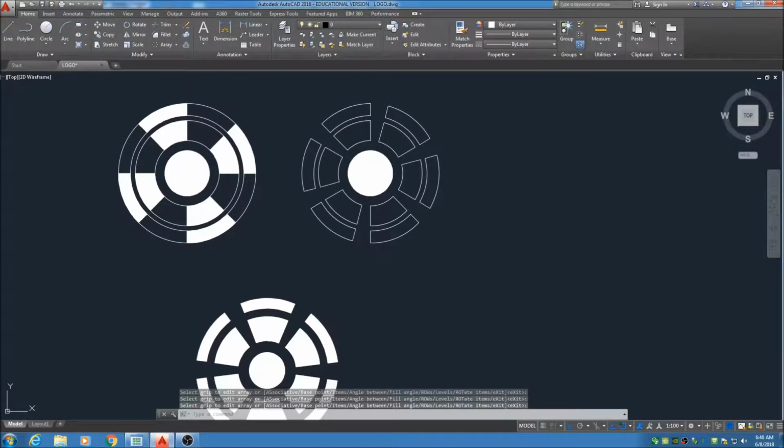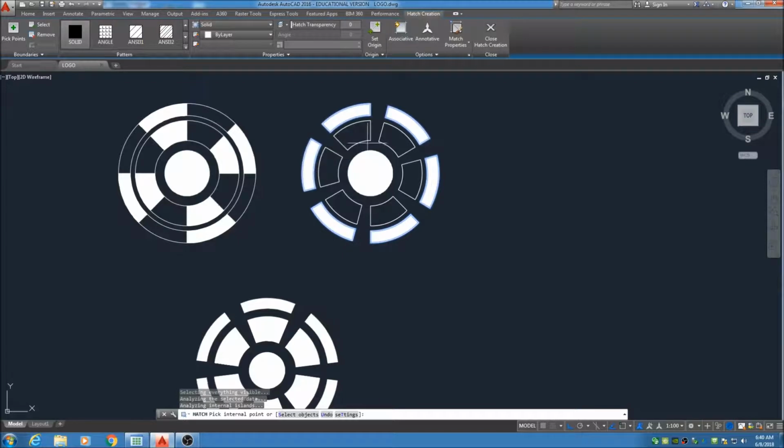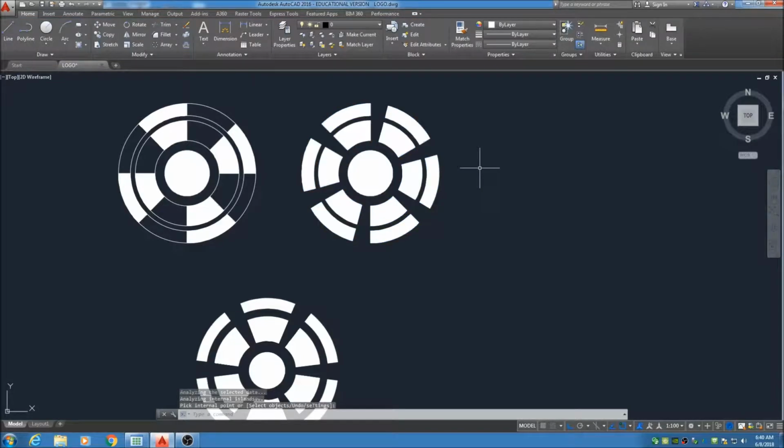First thing is to save. And now we go back in and we use the hatch tool on solid. Go. And I think I'm going to make this one solid entity. So I'm not going to hit spacebar in between. I'm going to just go like this. Work my way around. Fill it in. And it's just adding these together as one giant shape right now. Spacebar to end the command. And of course, Control S to save.